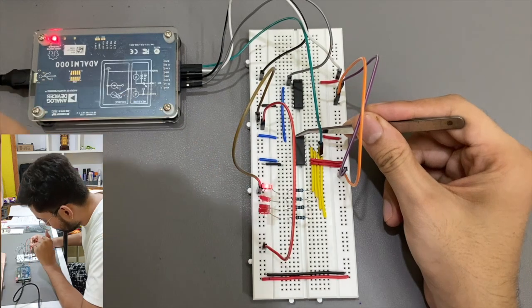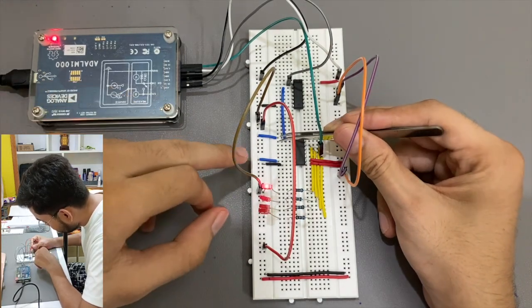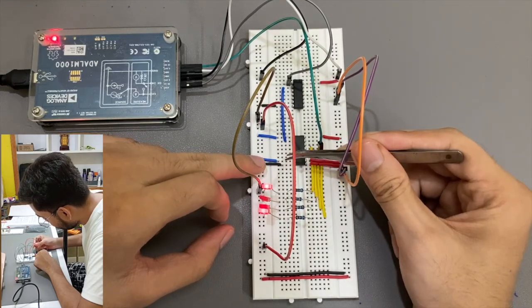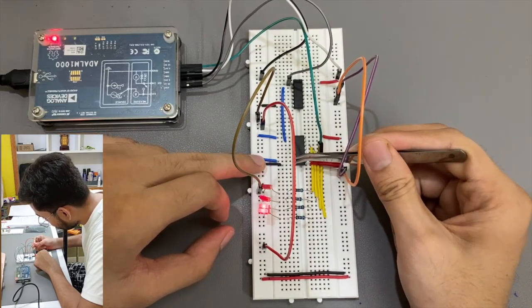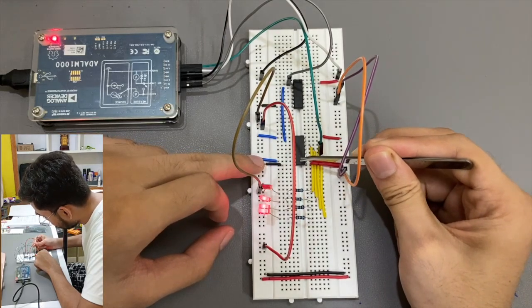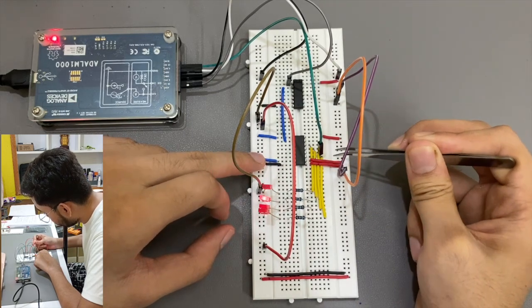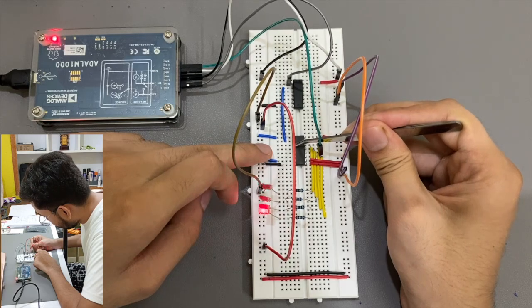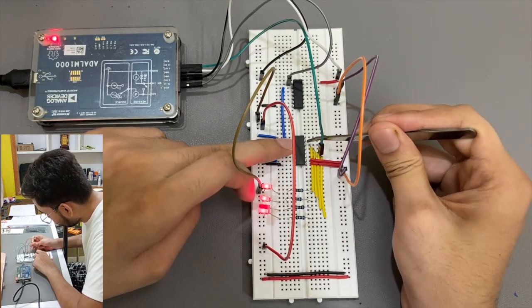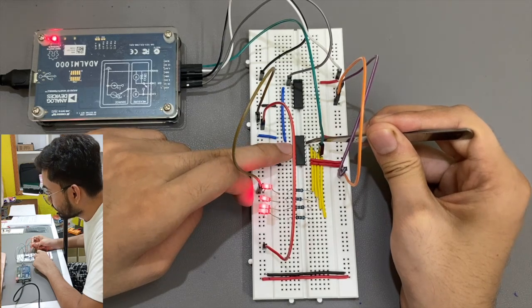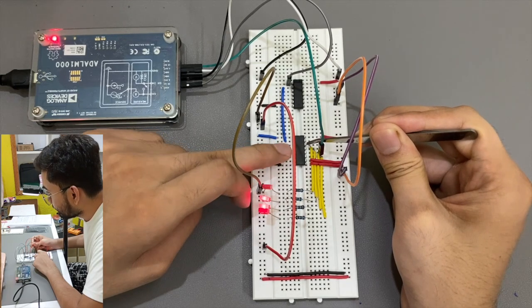The first pin of 74LS163, which is the clear pin, is connected to an input voltage, or set high. The 8th pin is connected to ground. The 7th pin, which is ENP, and also the 10th pin, which is ENT, are set to high. The 9th pin, which is the load, is connected to input voltage. The third, fourth, fifth and sixth pins are the inputs, and 14, 13, 12, 11 are our outputs, in which 14 is the least significant bit, LSB, and 11 is the MSB, most significant bit.